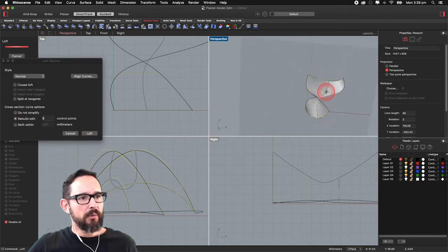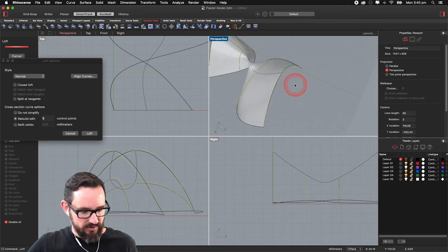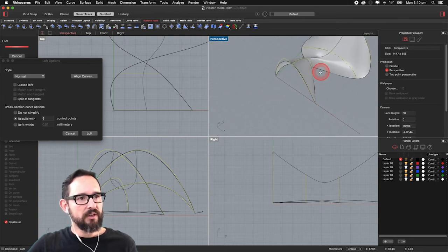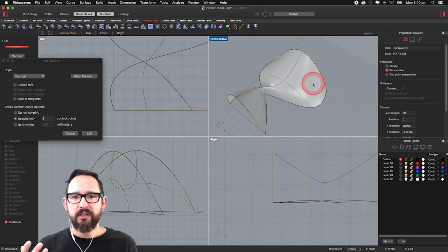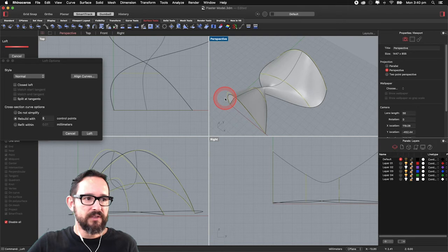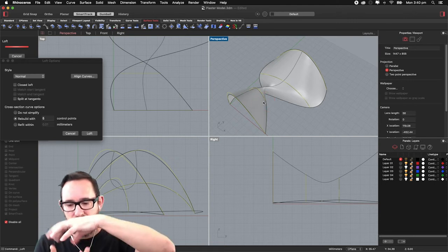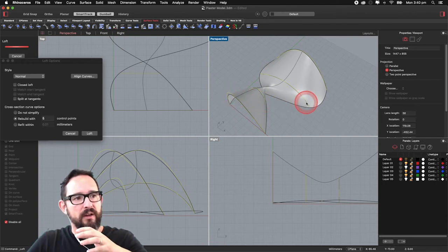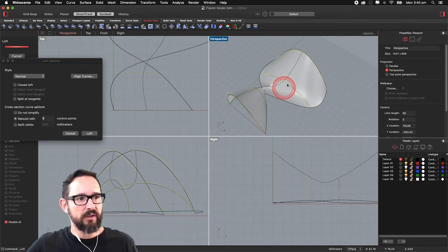So now we have already a problem here. This is interesting because it's not that something is wrong with the curves, it's something that we did wrong, actually. All curves have a start and ending point, right? Where you actually choose that starting and ending point is while you're selecting the curves. So if I selected this curve starting point here, but then the ending point of the next one, the first point when I selected here, that's why it tried to bring the starting point from here to there, and that's why it brings that kind of twist into the surface, right?